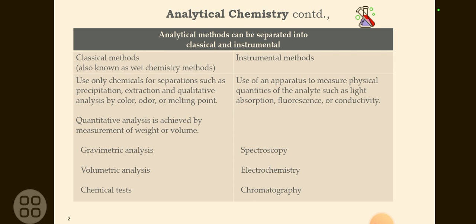And whenever we analyze FTIR, first we will run the standard material spectrogram, and also we will run the sample, the test sample spectrogram. So we will compare both the standard spectra versus the sample spectra, and we will see the correlation of that particular spectra.